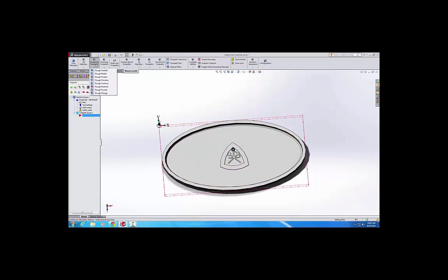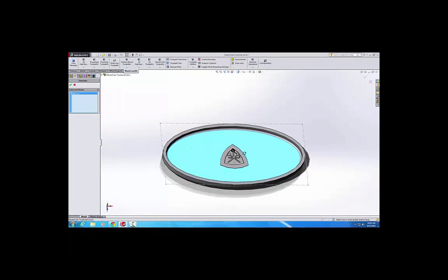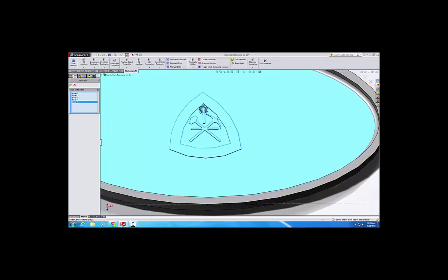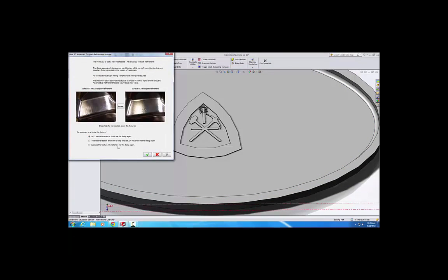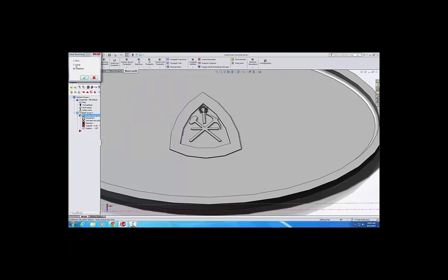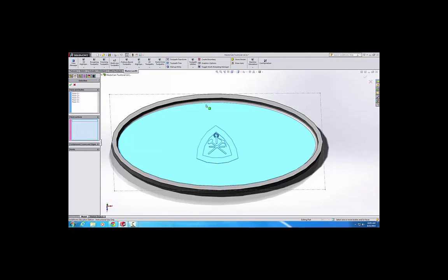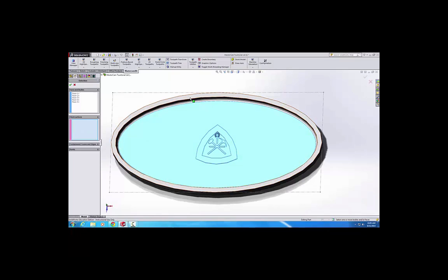You go to Roughing Toolpaths here, and you click Rough Parallel. You can name it whatever you want. And now select all the surfaces in here that are going to be roughed out. Hit the green check mark. Don't worry about that. This is a cavity, so we're going to select cavity and then hit the green check mark. The check surfaces are the surfaces that we specifically want to avoid, and that is going to be this outside lip of the part.